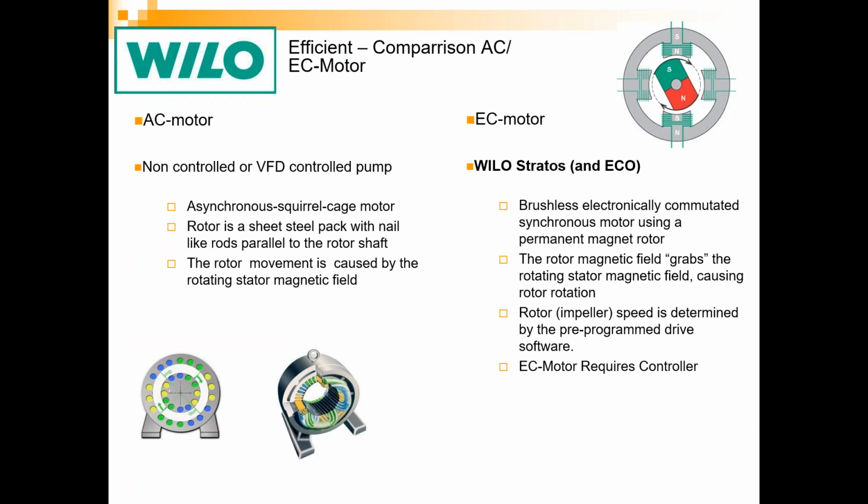You can destroy a pump, or you can make it so it needs to be cleaned more often. There's a lot of ramifications for doing that. So when you are looking at some of these high efficiency boilers, and especially if you're looking at electronically commutated motor pumps, you really need to be looking at, in my opinion, magnetic separation if you do have any type of ferrous material in those lines.